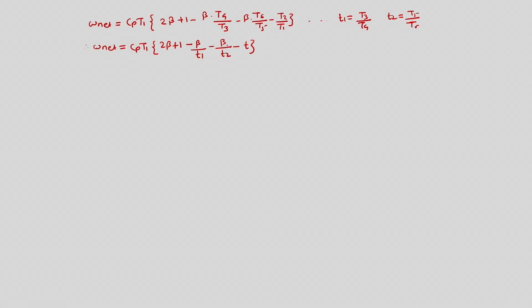So here we will say that we are working with same or constant Cp, beta and T. So the variable is only T1 or T2. So we are not altering compressor work, we are not altering the maximum and minimum temperature ratio, we are not altering the working medium. So we are just altering the pressure at which we would be doing the reheat. So here we are just altering the exhaust temperature to the high pressure turbine.